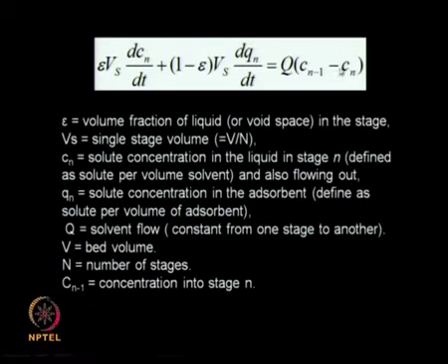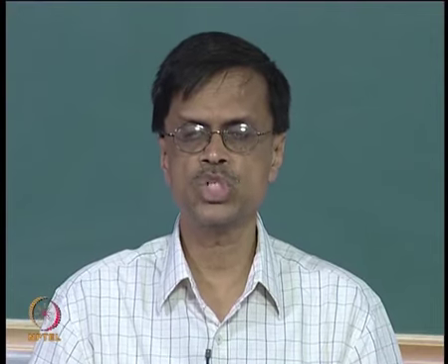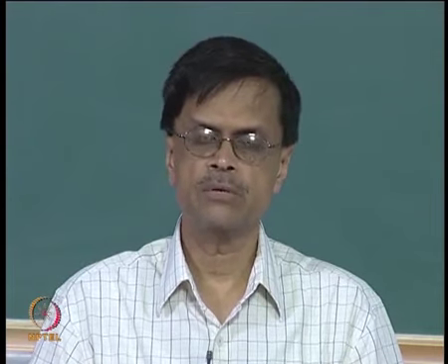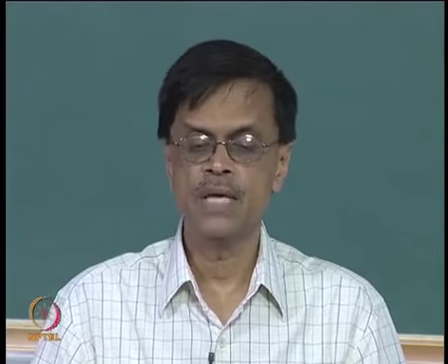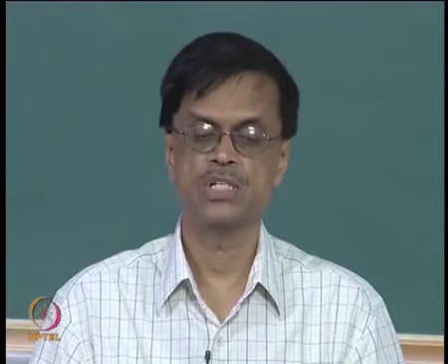One interesting point you need to note: the concentration of the solute inside stage n is the same as the concentration of the solute leaving stage n, that is why here we have put Cn as well as here we have put Cn. So please note that. In an ideal stage process, when there is an equilibrium between two streams or phases, the concentration leaving is the same as the concentration inside the stage. By doing that we end up with this type of differential difference equation. This is a difference, this is a differential equation.